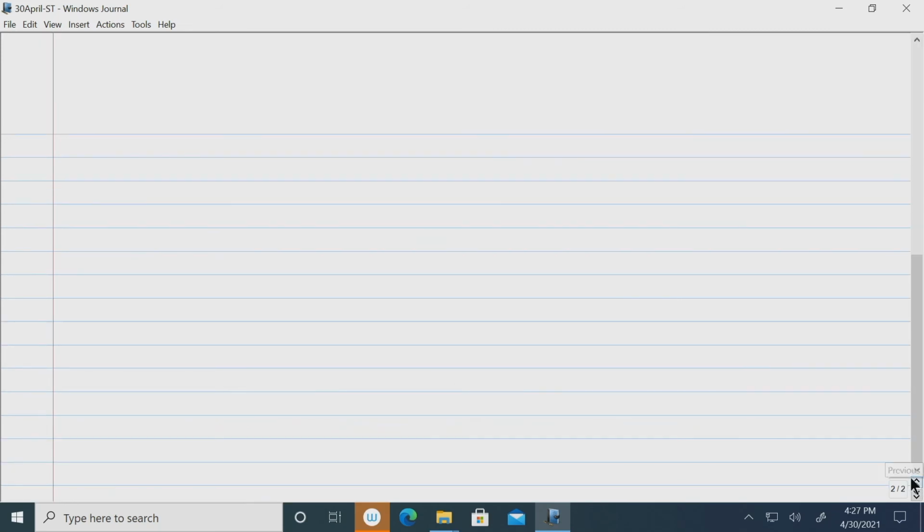Okay. Now, calculate n theta. The expression for n theta we already derived, and this is found out as minus W g r divided by 1 plus cos phi plus W g r cos phi. Okay. So, this is the expression for n theta.